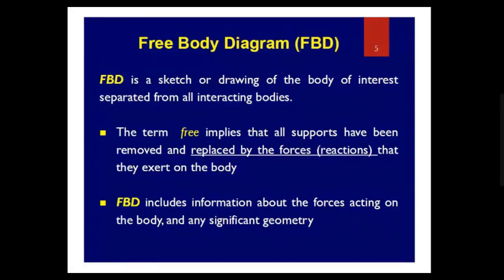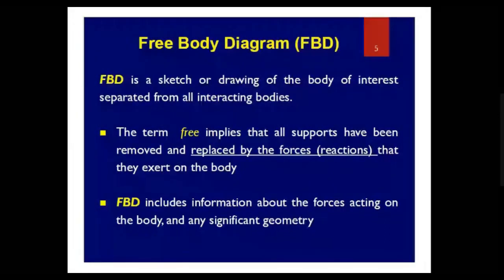So whenever you are drawing the free body diagram, you have to separate out that body from all the surrounding bodies, including the supports. And then, in order to mimic the response of those surrounding bodies and supports, you have to apply the corresponding forces or the reaction forces.